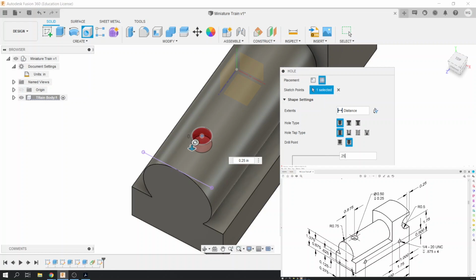This picture shows you the diameter, and according to my drawing, it's saying it should be 0.5 in diameter. And then if you've ever used a drill bit, what you'll notice is that drill bits have a pointed tip. So I'm going to just ask that you turn off the pointed tip. To do that, you just change this to 0.